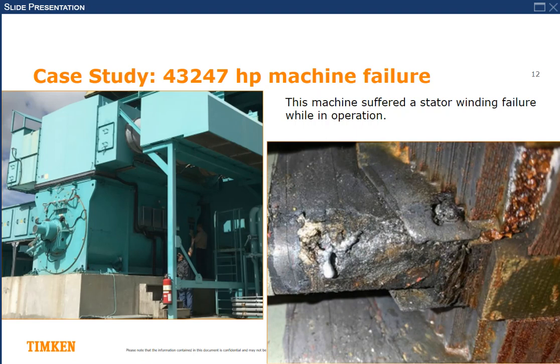Unfortunately, it's 10 years old, and it suffered 3 failures already, which is quite surprising for such a large machine. Typically, with this class of machine, you would look at first stator winding failure after maybe 30 or 40 years. Fortunately, what happened in the history of this machine is they had a defect on the internal cooling fan of the machine, and it failed twice.